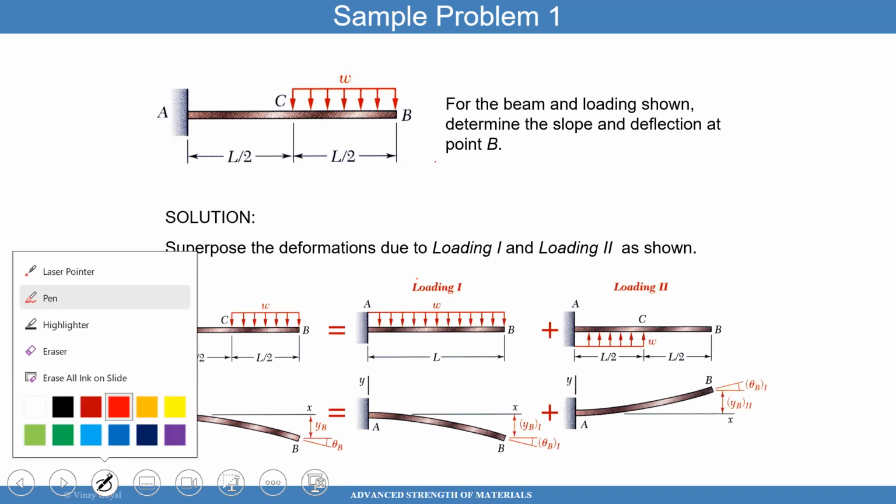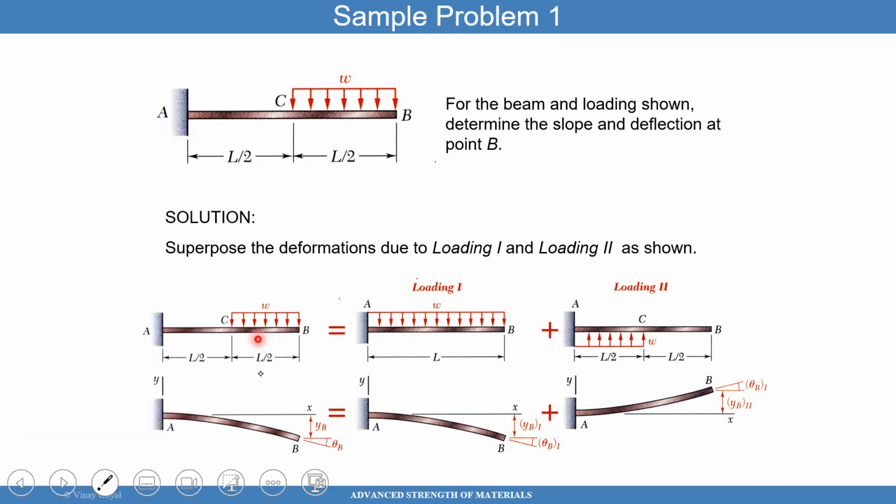So what you could do for this example problem is convert it into two problems. You have the problem here, and we can break it up into this problem with loads applied downwards, and subtract the load going upwards. Solve this problem and this problem separately using deflection theory, and just add this deflection to this deflection to get the total deflection. That's one way to do the problem. I'm showcasing this one because a lot of books have the solution for this one, and then you can add them up to get other solutions that you may not have in that table.